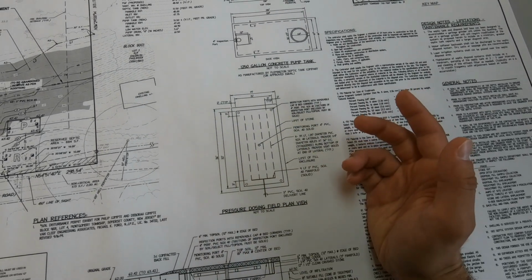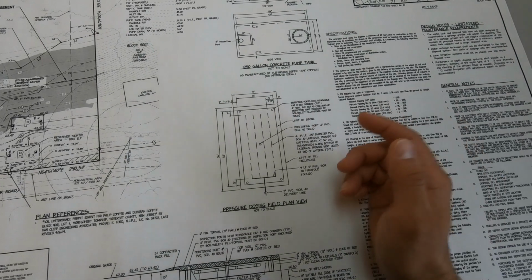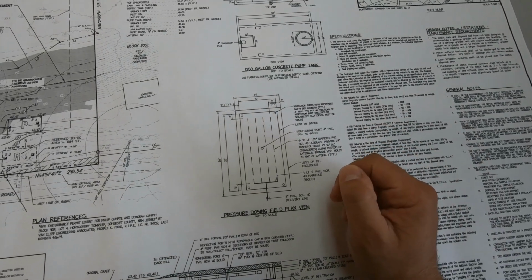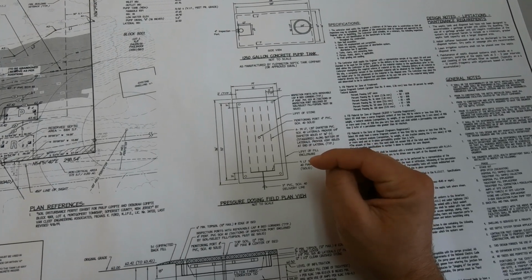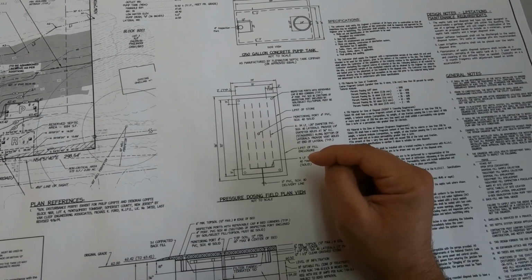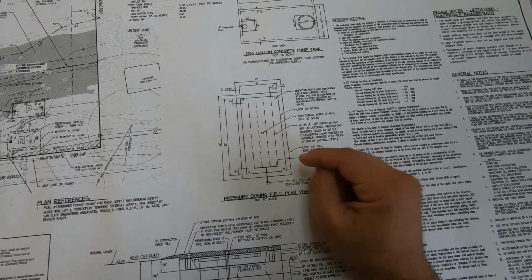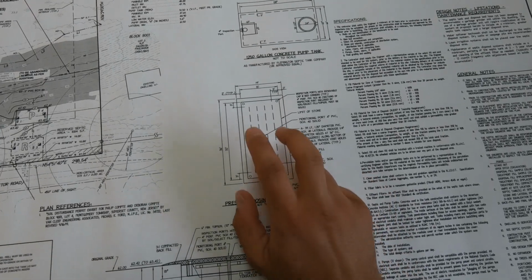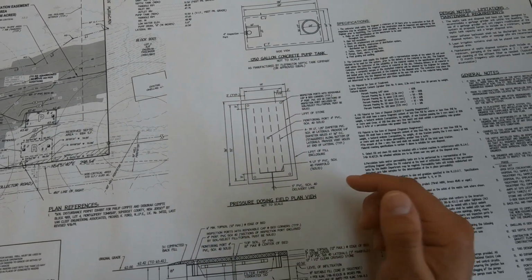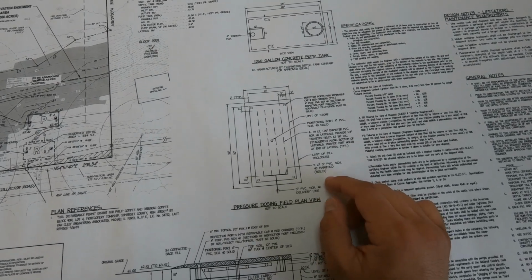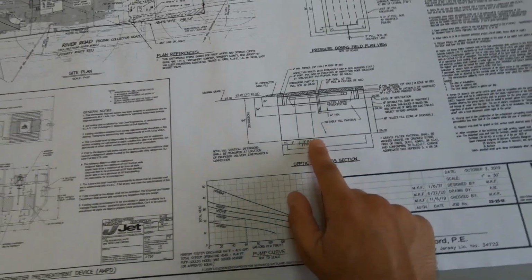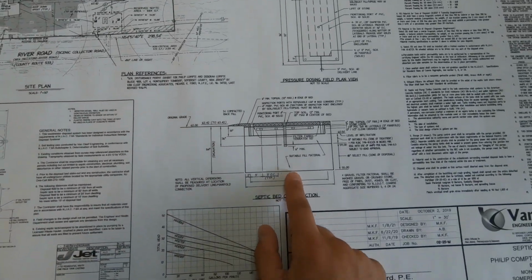This isn't so important where it's located as long as there is a deep inspection port, right? That's important for checking out the field or taking a look at it, doing a detailed inspection later on if needed, all right? So deep inspection port and then 4 corner ports that just extend down to the sand or topsoil select fill layer. All right, here you can see another cross section for the bed.